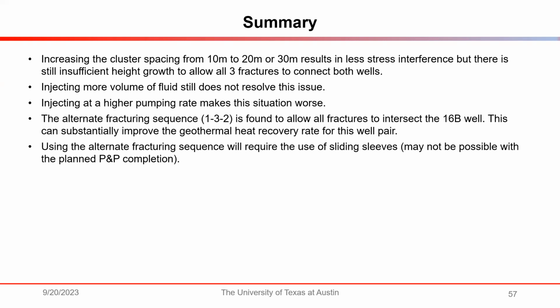Well, a standard thing we do in our modeling is we don't quite use the cubic law. It's pretty common. Like if you look at the core, in either shale or recently in FORGE, they don't actually see one planar fracture. They actually do see a swarm of planar fractures. And so if you're distributing the flow across more fractures, or the fractures are more irregular or branched or something, then it's not just flow through a slot anymore. And that could create additional viscous pressure drop.